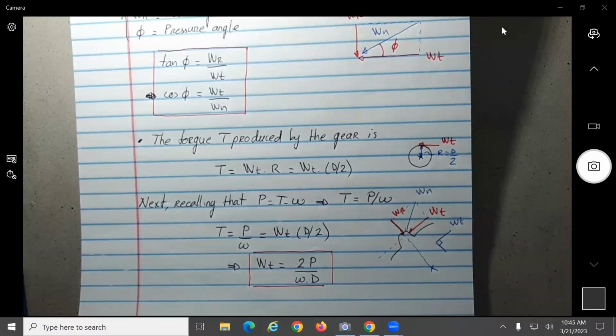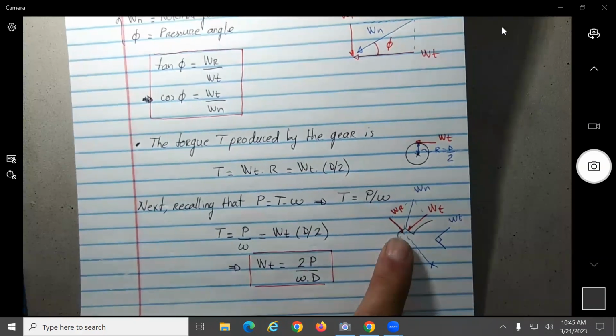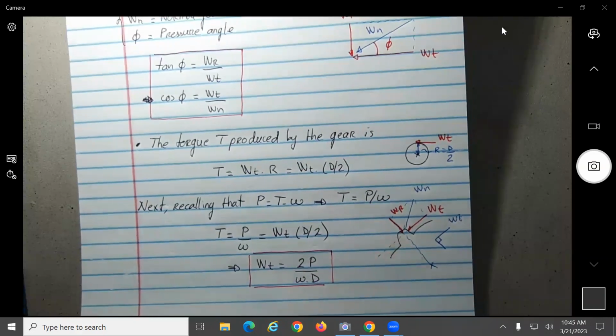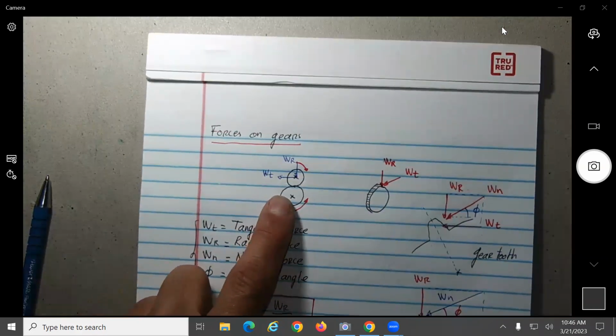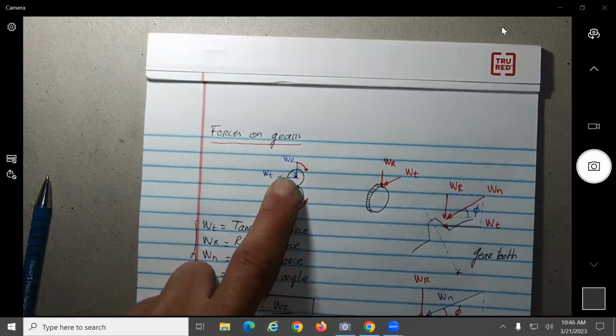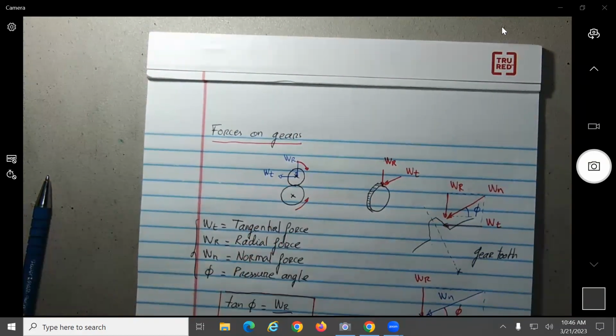You can have a gear for which each one will have a testing that will give you the resistance of the force for each one of the gears. I mean, it's more complicated than we're going to go. So, for example, if you look at the rating of gears, do you think you can put any number of teeth on either one of them, or do they have to be a certain combination? There's a certain combination based on the ratio, no? Okay, so it's not that you can put anything.